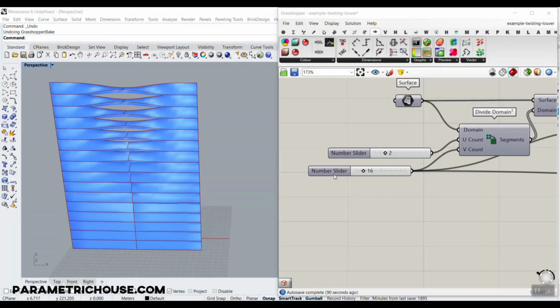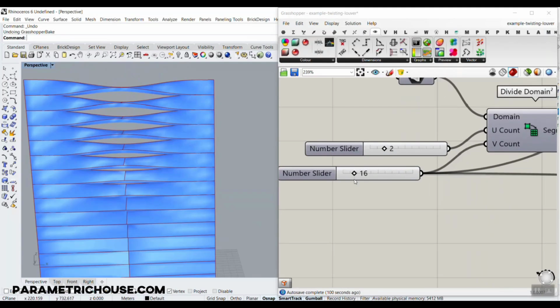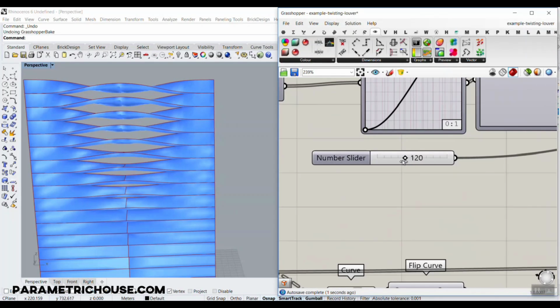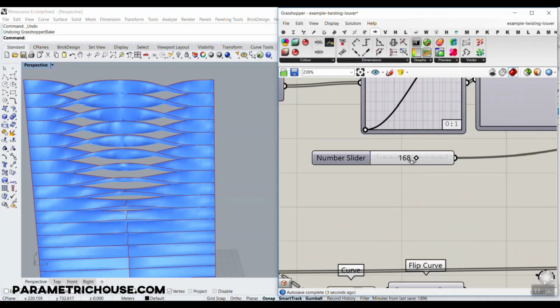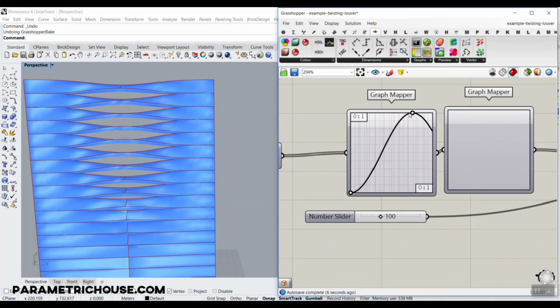In this Grasshopper tutorial, we want to model a parametric louver. So you can see that I can change the number of the louvers here on the surface. I can change the degree I want, so I can just change the degrees here. And I can also change the distribution.